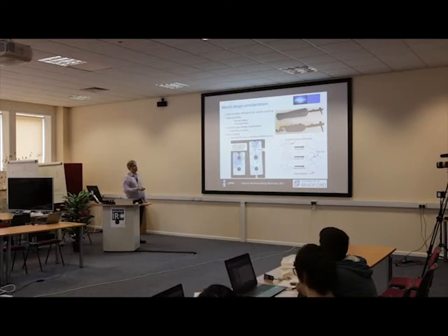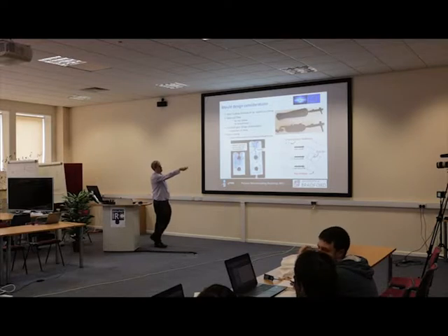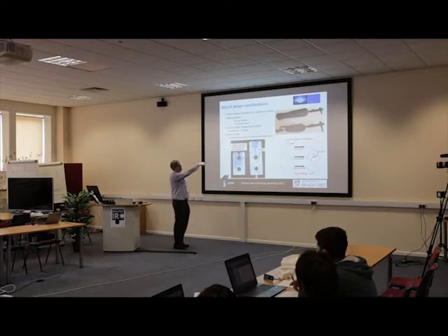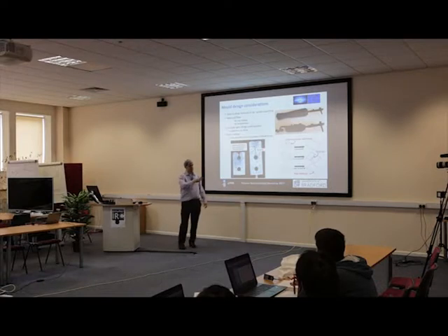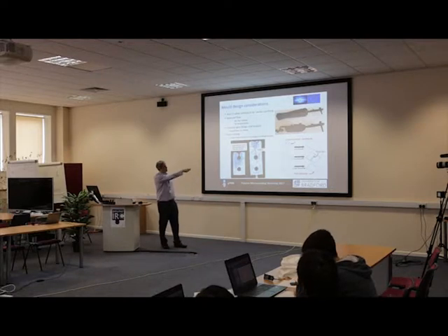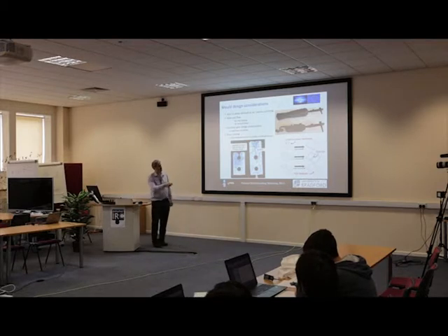We also have to look at the size of the gate and the gate location to avoid problems like this, which is a jetting behaviour. So rather than a nice uniform filling pattern that we see on the top part here, particularly for fibre filled materials, we can see this kind of snaking behaviour. So the material will snake into the cavity. So effectively now you've got a whole mass of weld lines all inside your part. So you have real problems with surface quality because you'll be able to see these kind of flow marks on the surface of your product.